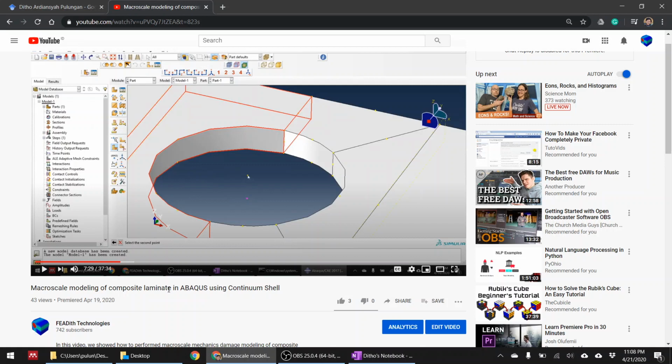But in terms of computational efficiency, of course, macro scale is better, right? It's cheaper in terms of computation. You can model a large part, yes, but if you want to go deeper, modeling the damage, for example the transverse cracking and the delamination, this is something that you cannot do with the macro scale. You need to go down to the mesoscale, so you need to model every single ply, and each ply will be connected using the cohesive behavior or cohesive elements. It really depends on how you want to do it.